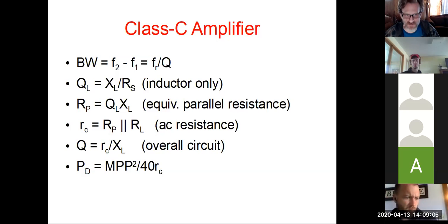One of our things, we can set it up on our inductor side as we look at our Q at our source resistance, and since we've locked in ideally what our inductor's value already is, we could very easily decide what our Q sub L would be, and then figure out any equivalency. These formulas are fixed and they're not that bad, because generally speaking, you first find out what frequency you want to establish. Then everything else falls into place and you design your whole circuit around that.